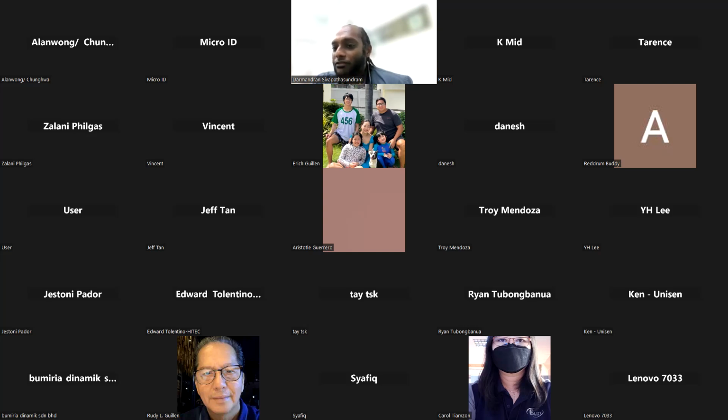You want to extend for the output, like if we say the mimic panels and all that. So the mimic panel, you'll be using an external relays board. There's another board which contains 16 relays. By adding those additional multiples of 16, you can add it as your automation section to indicate the mimic part itself. But the IO board itself, the individual board, for the emergency panic, those are 5 outputs. So I'm not sure if you're talking about the panel for the mimic or alerting and all those kinds of things. That is a separate relay board.